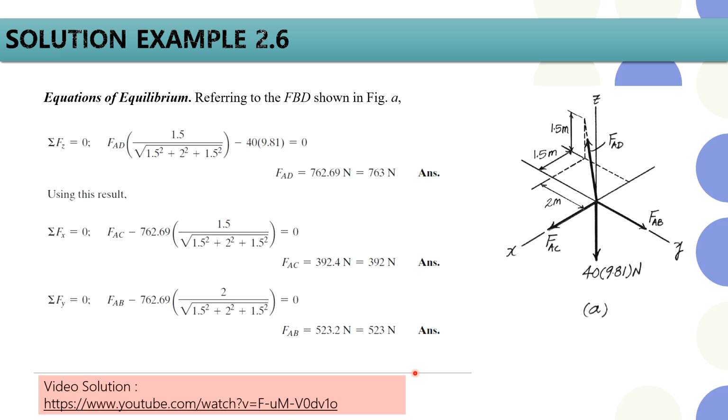Then we learned that the most critical tool in your statics is the free body diagram. You just need to remember the 3 steps. You need to isolate the particle, draw every active and reactive force, and label your knowns and unknowns. Once your diagram is drawn, the calculation will be straightforward.